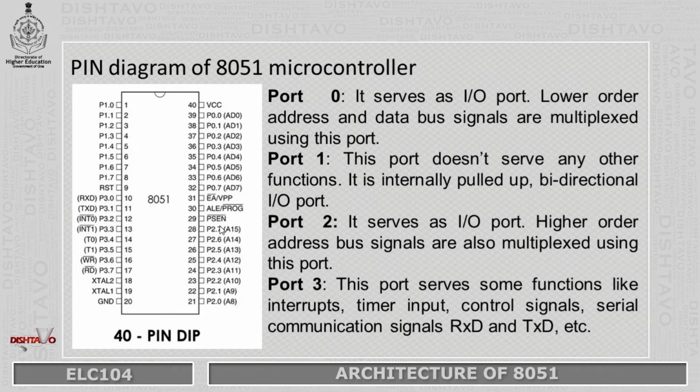So now let's see the functions of the various pins. First and foremost, let us see the ports, because ports are very important here. So there are altogether 4 ports. These ports are named as port 0, port 1, port 2 and port 3. Port 0 serves as an input-output port, and it also serves as a lower order address and data bus which